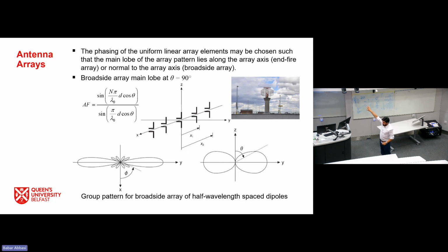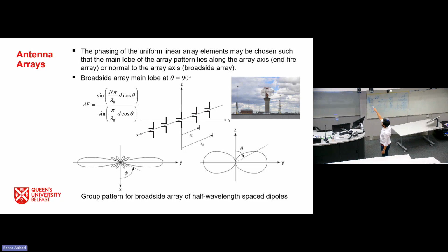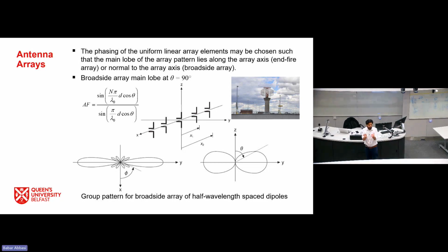These nulls are okay, and they can serve some uses, but it's too risky for building an antenna system that has this many nulls. So it is not good enough to capture anywhere along the x-axis and y-axis, only good enough along the y-axis, not along these sectors from top and bottom.